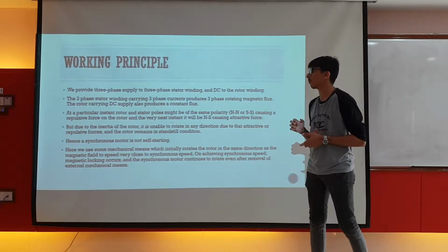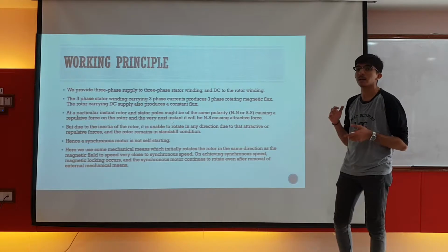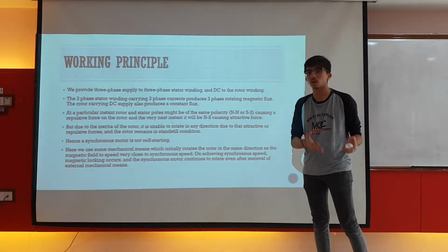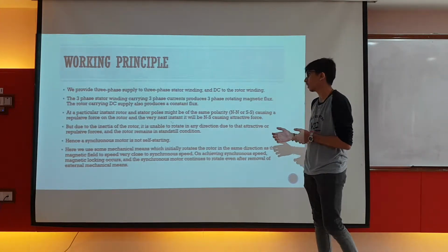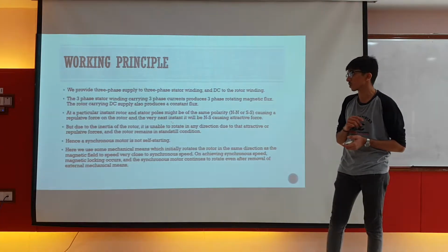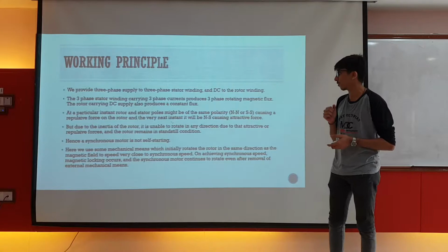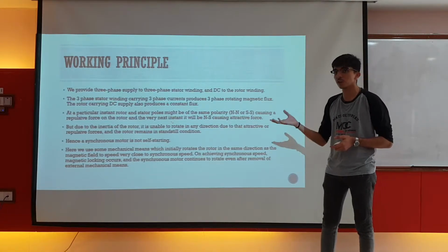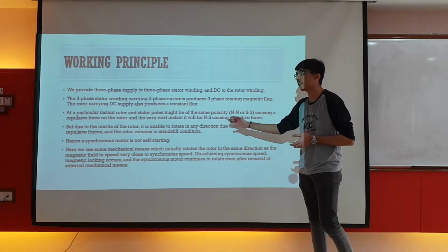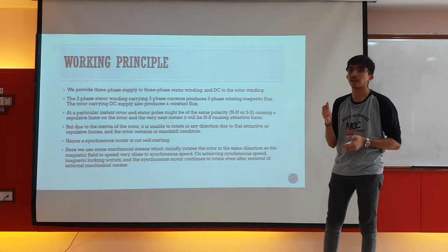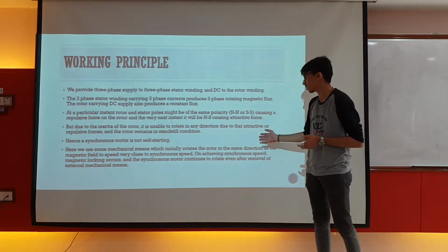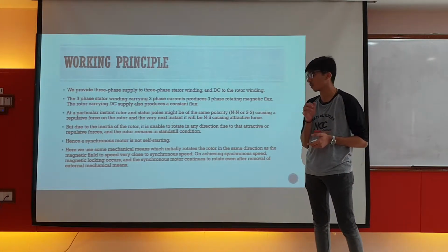At a particular instant, the rotor and stator poles might have a similar polarity, which is north and north polarity or south and south polarity, causing a repulsive force. And the very next instant, there will be a north and south polarity, which will cause an attractive force. Due to the inertia of the rotor, it does not rotate in any direction despite having attractive and repulsive forces. So it will be in a standstill condition.